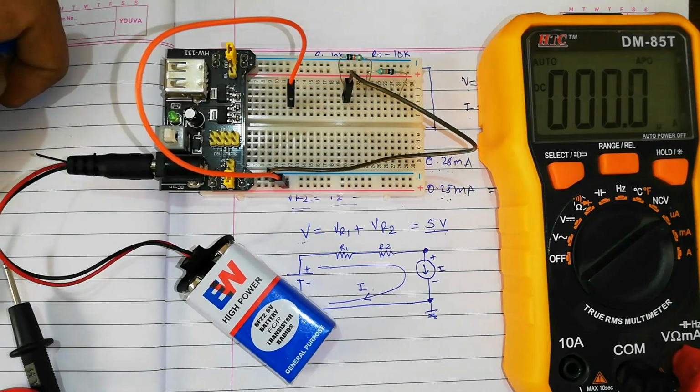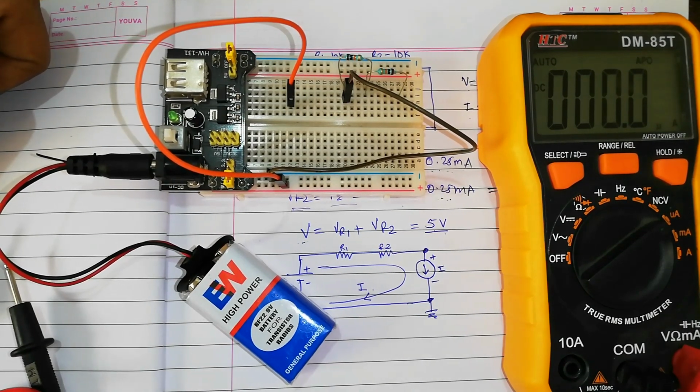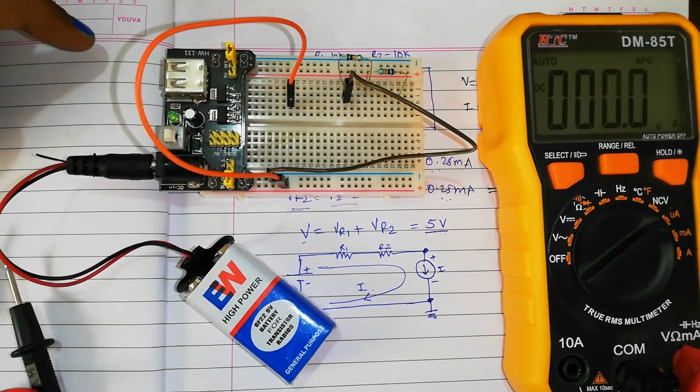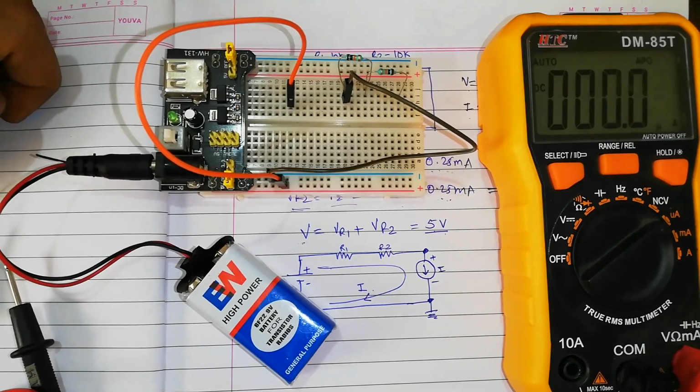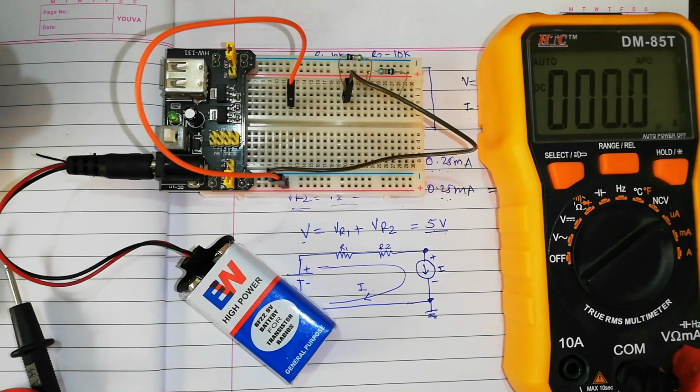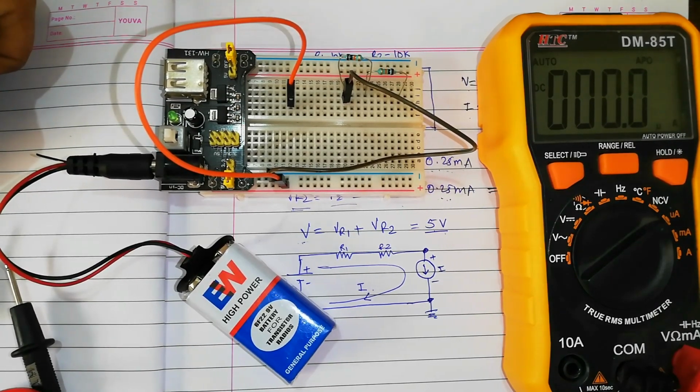They are quarter watt resistors each. It means they can bear a maximum of 250 milliwatts of power. So the square of the current flowing through them, I squared times R, is the power dissipation in each resistor, and that value should be less than the rating given by the manufacturer. We have explained that in the previous video, and make sure that you cross-verify for yourself. That is an exercise for you.